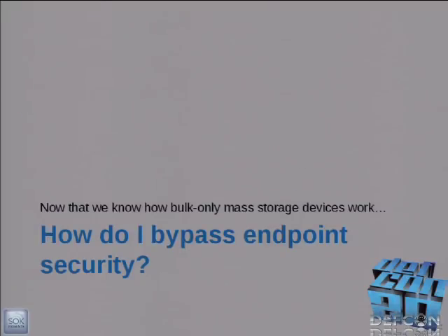By the way, if you're cheap and you want to view all this lovely USB traffic and you have a Linux machine, if you don't know this, you can use usbmon. So if you just do a modprobe usbmon and you fire up Wireshark, guess what? All of a sudden you have a bunch of USB buses available for you to trace this stuff on. Comes in handy. Of course, a hardware USB tracer would be nicer, but they're a little bit more expensive than free. So. All right, enough of this background stuff.